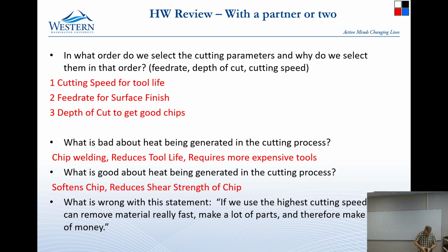So, as you are cutting the cell, you can think of a cell like that. As you come through and you cut the cell, typically, because the fiber orientation makes it, in the thin wall, difficult for the honeycomb to be cut. Also, with the fibers, we end up using a highly negative rake angle, so it kind of mushes into that cell.